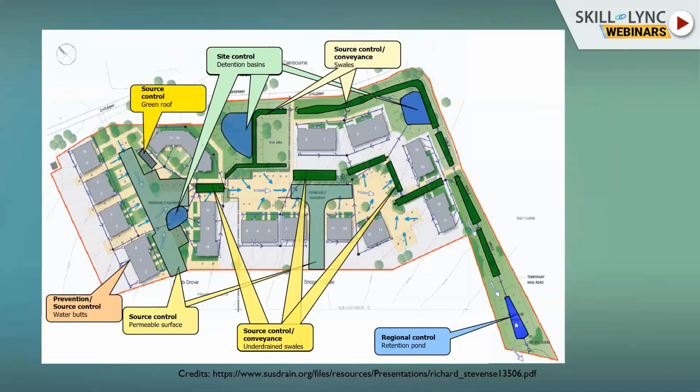And sometimes, as we said, the climate is changing and more rainfall is coming. So even sometimes the rainfall that came here and the flow it accumulated overspilled. In that case, we connected this pond to a water course, which was initially connected when we had those pipes and manhole system.